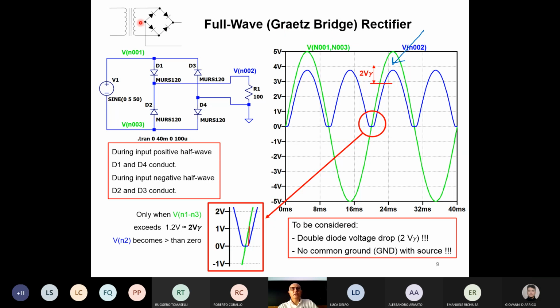It's very useful because it's using only the minimum amount of copper at the secondary winding, but you must accept the double voltage drop. If the output voltage is small, this error can be very large, and you have to consider it. If we are using a high voltage, you can neglect, again, this double voltage drop, this 1 volt voltage drop. Okay.